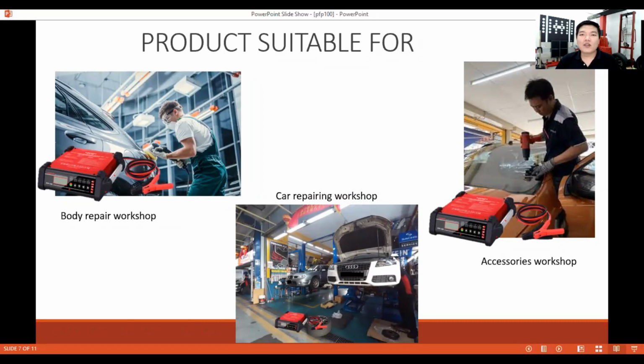They keep on changing the battery. When the battery is always opened and put back, the module will slip up. If it's like this, soon you will have many problems with the immobilizer. You have key immobilizer problems, control module damage problems, and so on. It will create many problems in body repair because of the battery voltage.